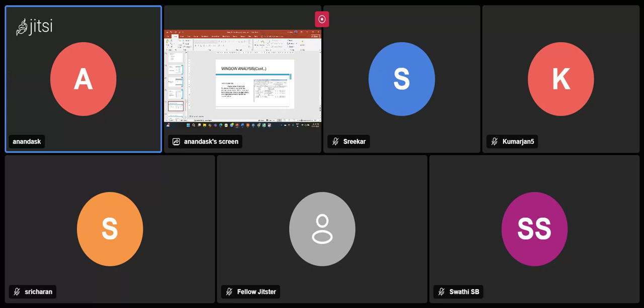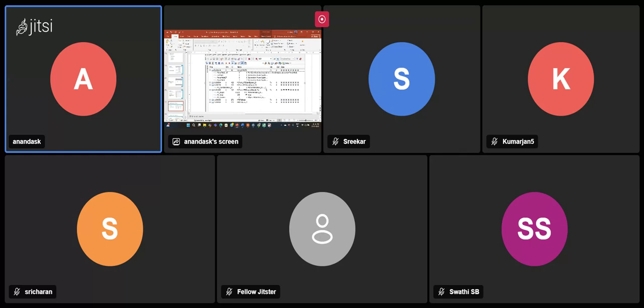And now we have the trace window we already discussed. So the purpose of the trace window is to record the bus activities during the measurement. All the messages received as input to a trace block are displayed as lines of text in the trace window. So now you can see we have the Tx messages and Rx messages here, and this is the information you can see. This information comes from the database.